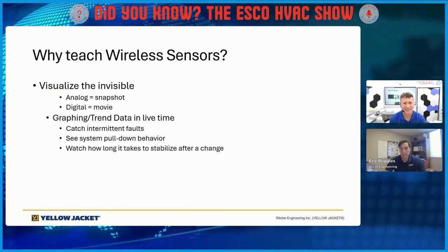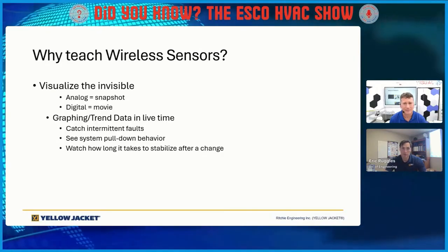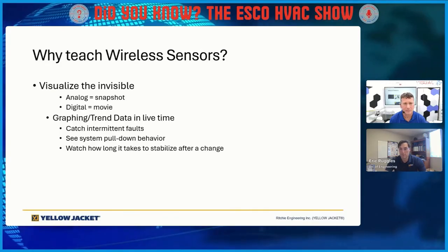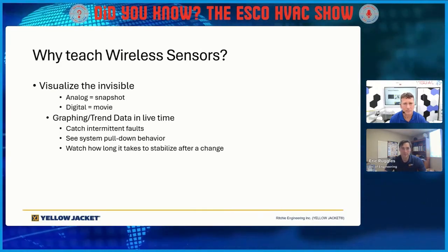We can take a data log and then put it up in a graph of everything if you wanted to. But you can see trends. You can see the compressor shut off and turn back on. You can see what happens when it doesn't start and why things equalize, etc.